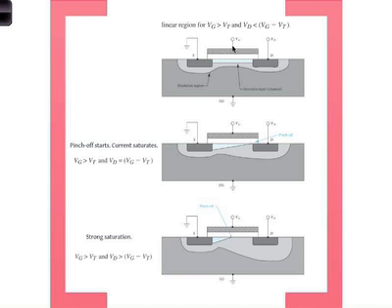So the picture is the following. You have a gate, which is essentially a metal. You have an insulator, which is the oxide. And then you have, in this case, a p-type semiconductor, silicon. That's it. So you apply a positive voltage. You create positive charges here. Of course, this is an insulator. Nothing happens here. You start attracting negative charges here. You apply positive charge here to induce a negative charge.